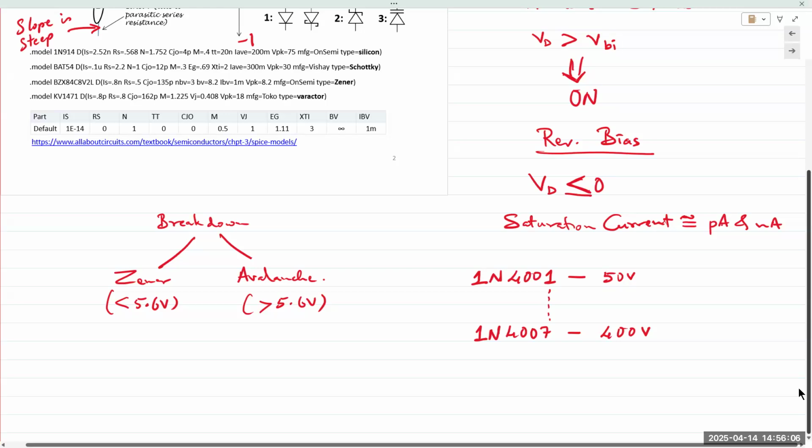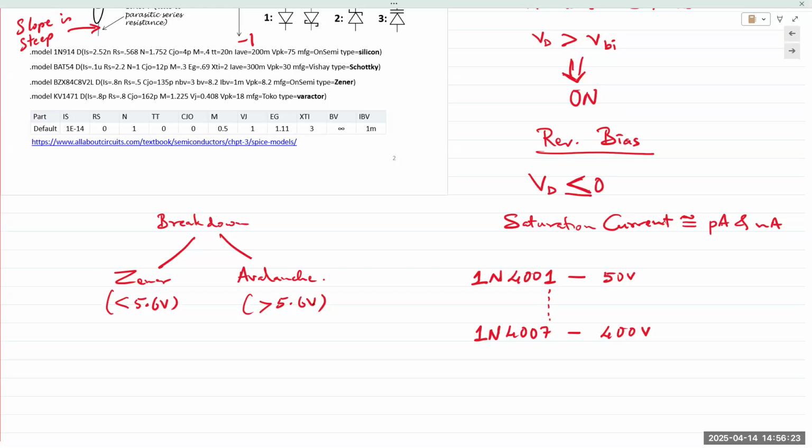The collision process is known as the impact ionization process, because more charge carriers are created with impact, with collisions. And as they collide with other atoms, those atoms are ionized because the electrons are popping free. So that is known as the avalanche effect. And the avalanche effect occurs due to impact ionization.